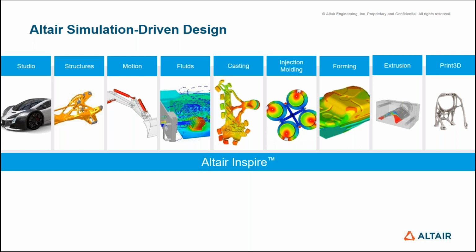Of course this concept generation is very important in any product development process, because only after that does the design validation come into the picture. If you get the right concept at the starting stage of your design, then with the help of topology optimization you can generate concepts which are mathematically correct. So what are the input parameters required for that? You need to define a package space. A package space is nothing but a design space where you can change the design and the loading conditions. With these two input parameters, the software will run the iterations at the back end, and it will give you an optimal design or optimum material distribution.